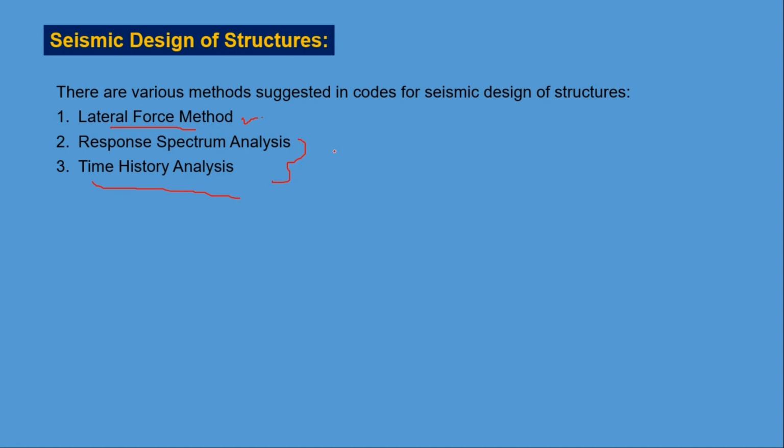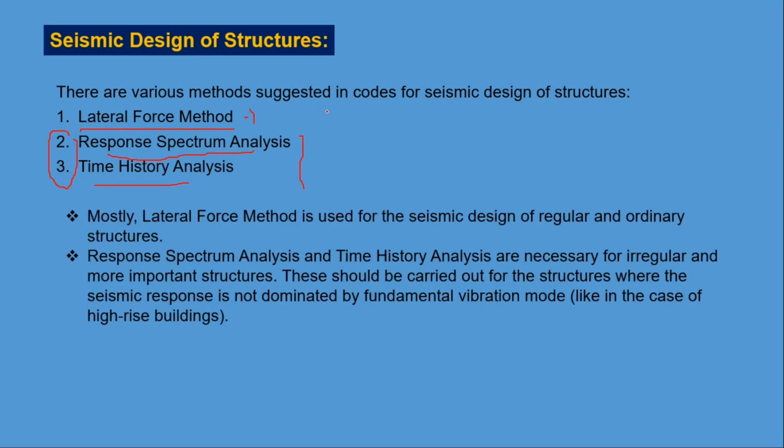And also for buildings in which the deformation or seismic response is not dominated by the fundamental vibration mode, we have to use these two methods. Mostly, if the code does not explicitly mention them, we have to follow the lateral force method because of the complexity of the other two.